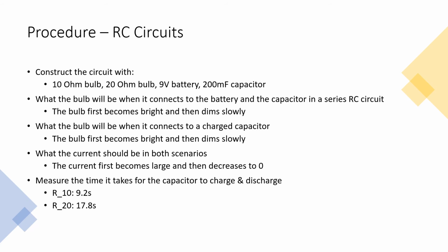And we measure the time it takes for the capacitor to charge and discharge. So for the 10 ohm resistor, it takes about 9.2 seconds. For the 20 ohm resistor, it takes about 17.8 seconds.